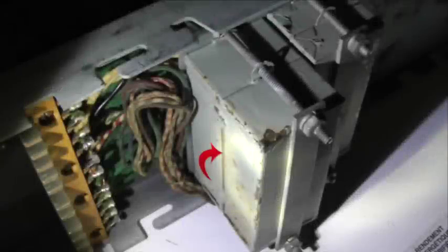Here are some other components mounted on the rear side of the switch base. This double box assembly contains the capacitor network, which consists of 3 capacitors, the tip, ring, and A capacitors. The tip and ring capacitors are 2 microfarad voice transmission path capacitors that isolate the direct current top battery supplies from each other while allowing the passage of the alternating current voice signals. The A capacitor is a 0.04 microfarad capacitor that passes a small amount of the ringing current back to the calling party, which provides an audible ringing tone.